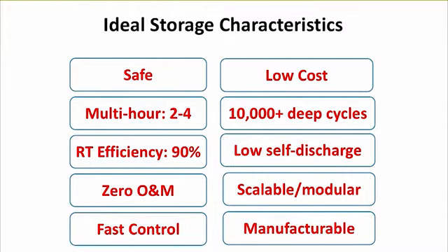Multi-hour, in order to go beyond the sort of transient functions that some energy storage technologies are well attuned to. Many thousands of deep cycles. If we think about that duck curve where I spoke about 2 cycles per day, if we start looking out over years, 3,000 something cycles would get you through 10 years at 1 cycle a day.